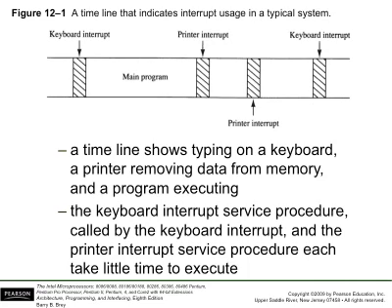You do want the interrupt service routine to be as simple as possible. Just deal with the device, acknowledge the interrupt, and get back to the main program as soon as possible. Otherwise, the efficiency will be very low because you cannot carry out the main task, which is executing your main program.